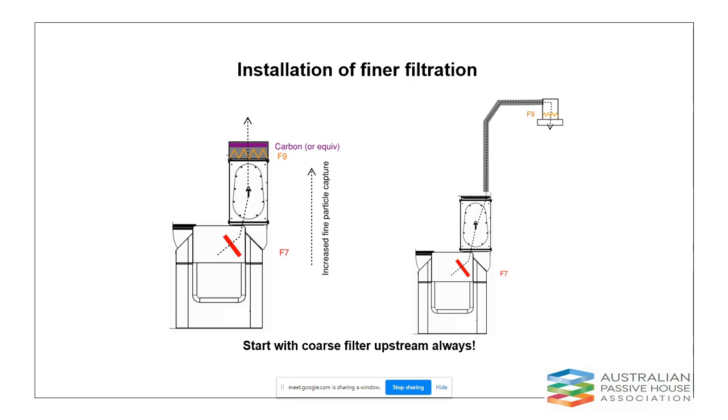One potential for this sort of application is that you could short-term retrofit something of this type, and you might even have a chance of getting something a little better than F9 as a bespoke solution. But as Cam said, it's not really a full solution if you're looking to take out all those really small particles.